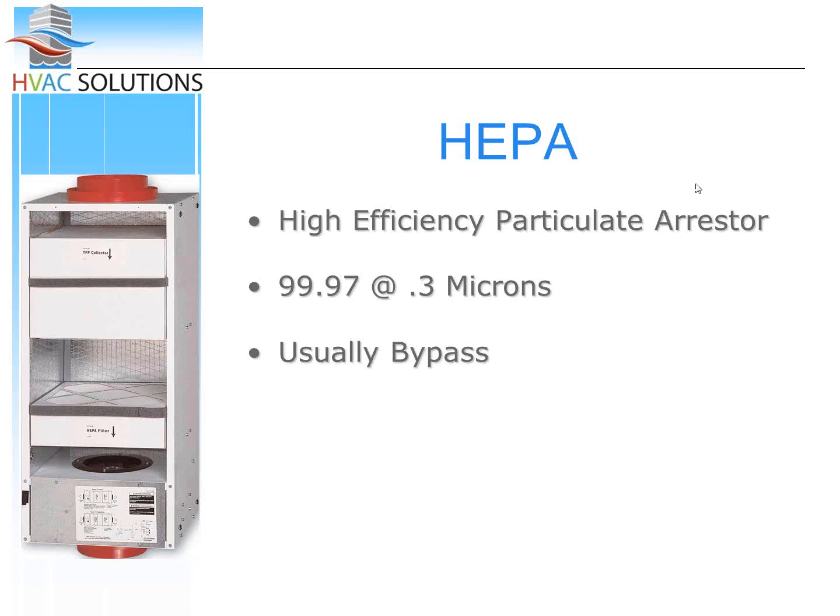All right, so electrostatic filters. The beautiful thing about these is that they're 1 inch. Occasionally you'll see a 2 inch. So this is a filter that slides into the existing filter grill, and then you run 24 volts to it, and it makes these filters much more efficient than a standard 1 inch filter.